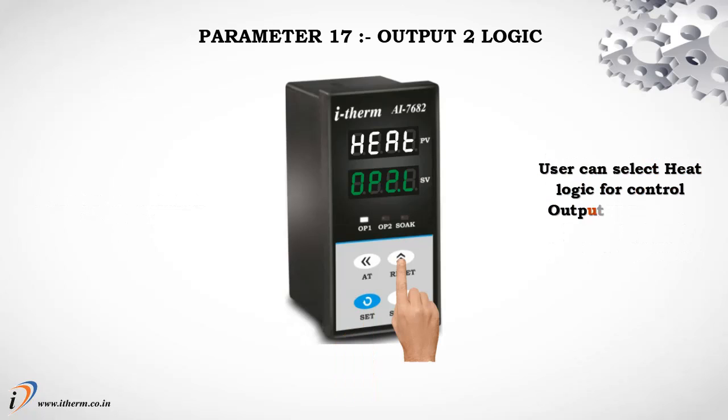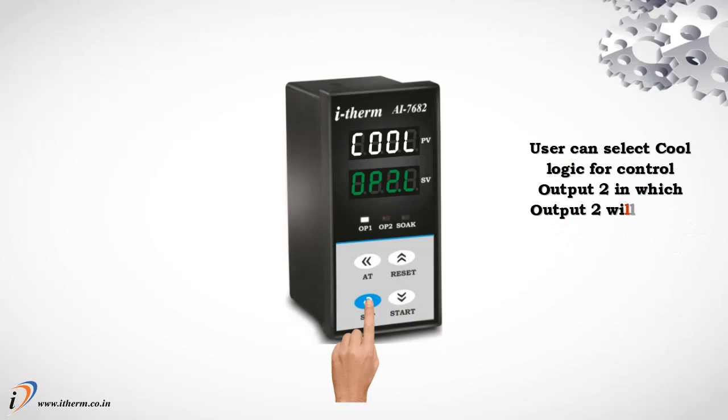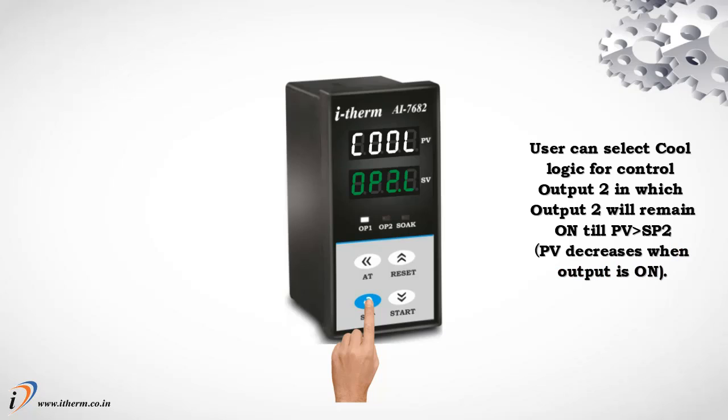Parameter 17, Output 2 logic. User can select heat logic for control output 2 in which output 2 will remain on until process value is less than Setpoint 2. User can select cool logic for control output 2 in which output 2 will remain on until process value is greater than Setpoint 2.